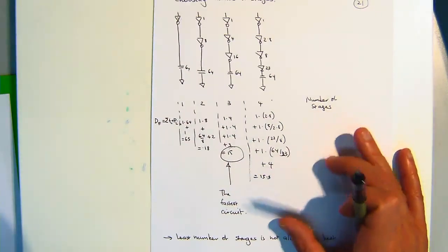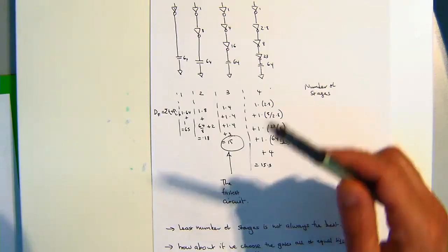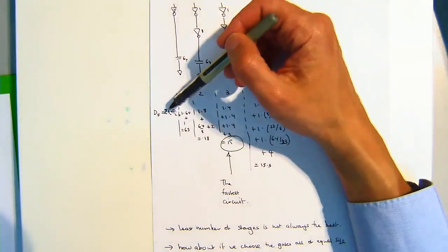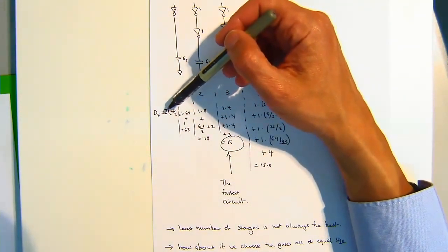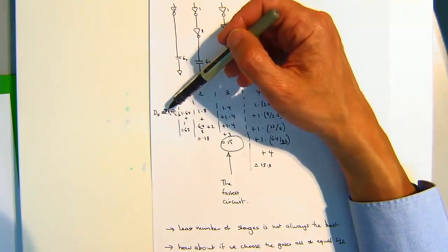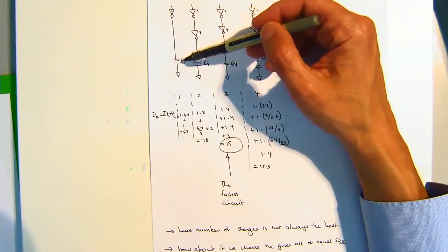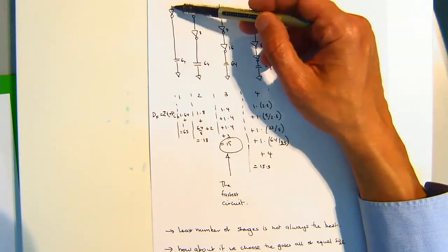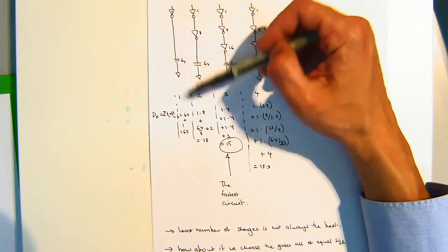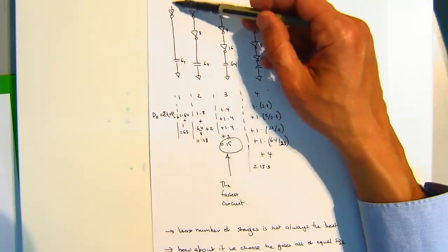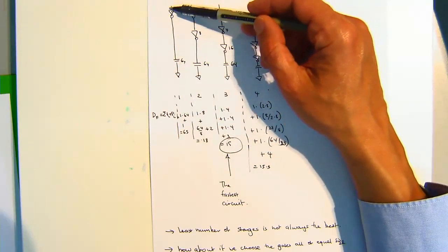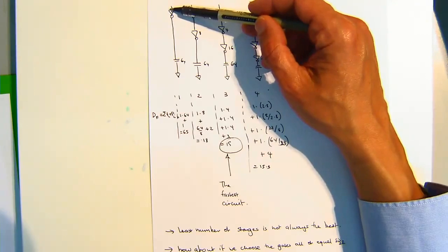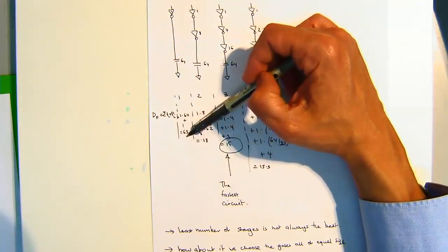in this particular case. And we know that Fi is what? Gi times Hi. What's Hi here in the first case? Input on output capacitance, so it's 64. So 1 times 64 plus the parasitic delay of an inverter, which is 1. So it's 65 units of delay.